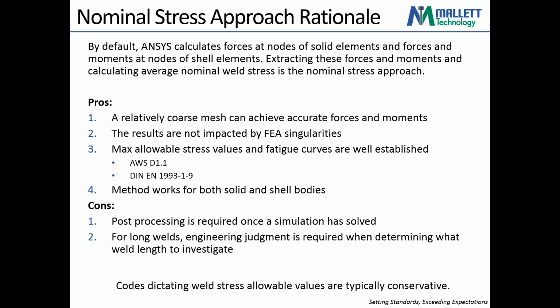As is standard in any FEA, if it's unknown how long to go, it's typically good to go less, typically good to go more conservative. So focus more of the worst case load in a smaller weld length.